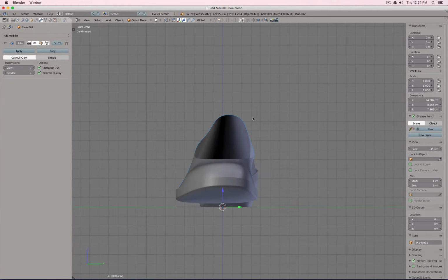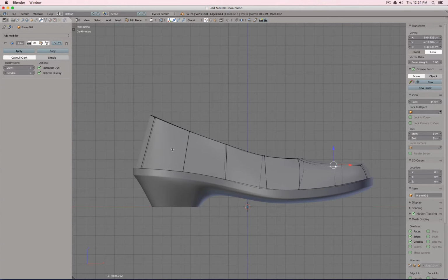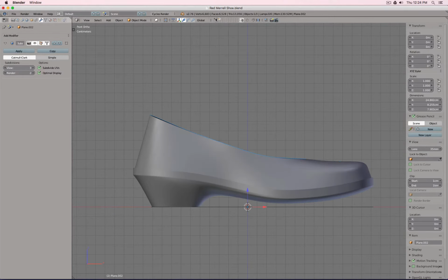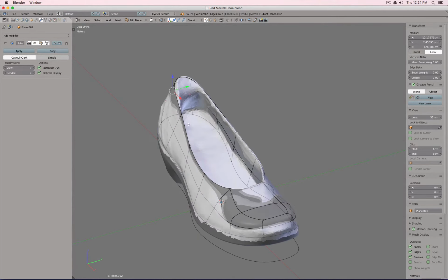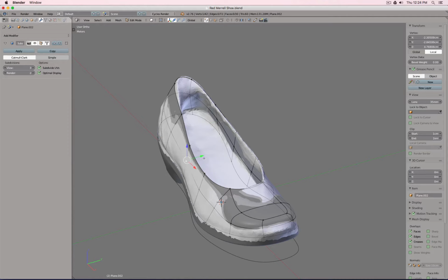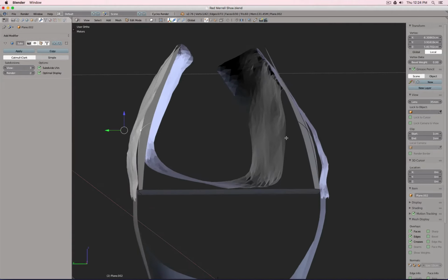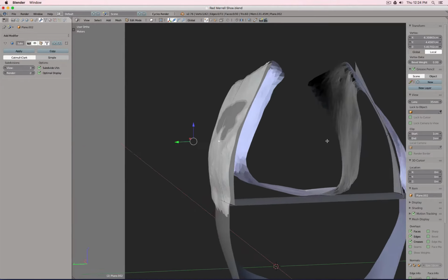Not too bad, it just looks too simplistic. Now you see it's way too straight. That's the reason why we can now create another loop cut, because with this additional loop cut we can start crafting our curvature out. And in this case, what I like, if for example you work with a 3D scan, I just go into cut sections so I can better see maybe where my surfaces should be.